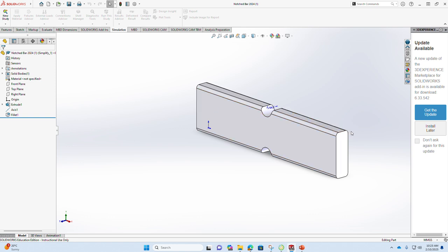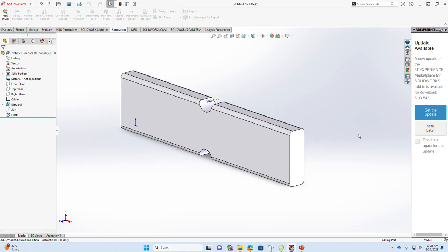For the finite element analysis, the first thing that you need is, of course, your part file or the geometry. This can be made in the regular way that you make any part file in SolidWorks. That's why I have skipped that part and directly imported the part file. But keep one thing in mind, that you always have extra features in the geometry that may not be important from an analysis point of view. So you may or may not actually want to replicate them, okay?